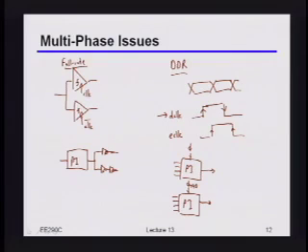But so what's kind of bad? What would start happening if you actually had to support that kind of system? Let's say even with a QDR kind of system, so quad data rate. How many phase interpolators would you need to support that? Yeah, you'd want 4 phase interpolators, right? If you have 8, you'd need 8 phase interpolators and so on and so forth. So first of all, what's the obvious thing that's kind of bad about that? Power and area. Yeah, power and area. Okay, and then the second one is mismatch.